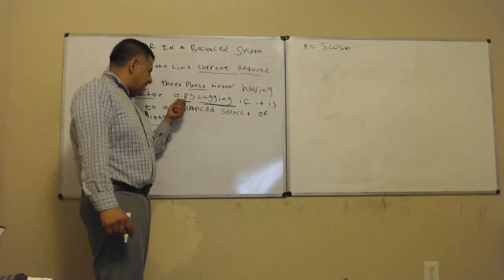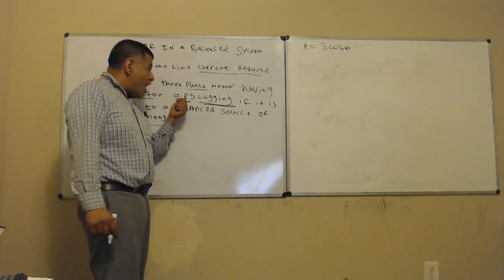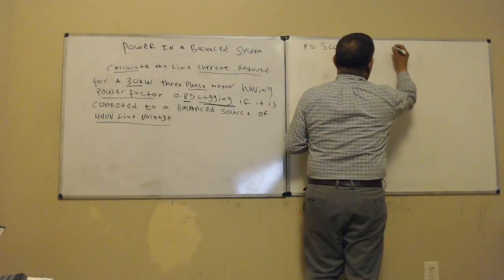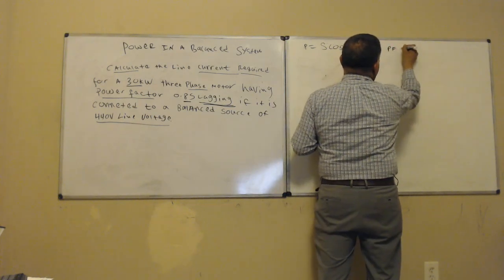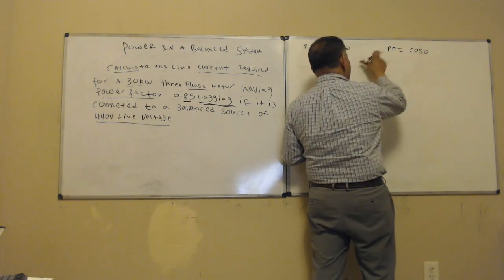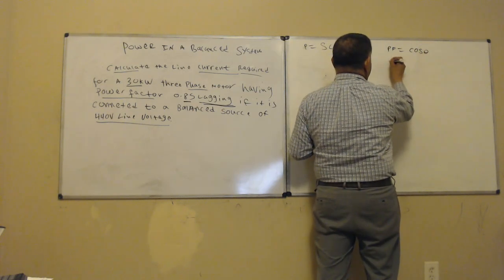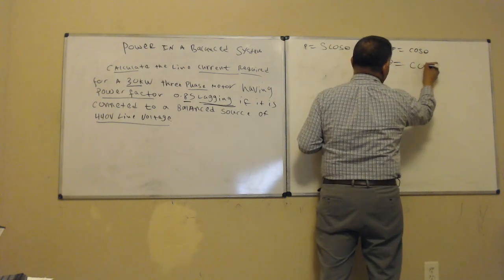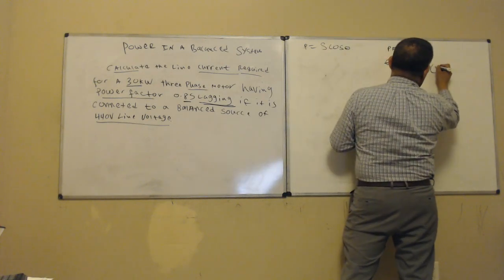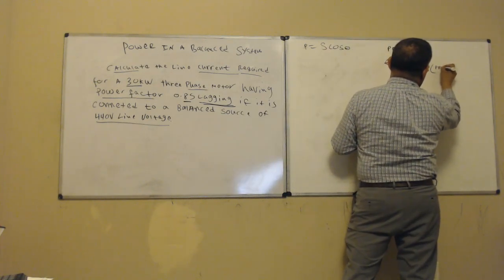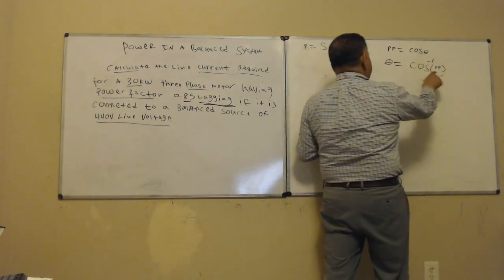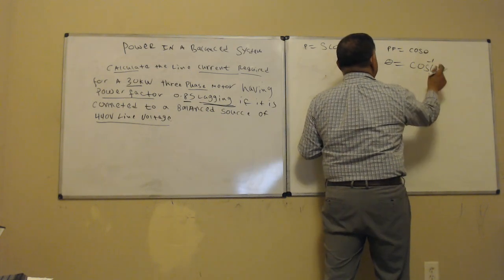It's not telling you that it's negative, it's just telling you that it's lagging, but the power factor indeed is negative. So power factor equals cosine of theta, right? Now take the inverse: theta is equal to the inverse cosine of the power factor.